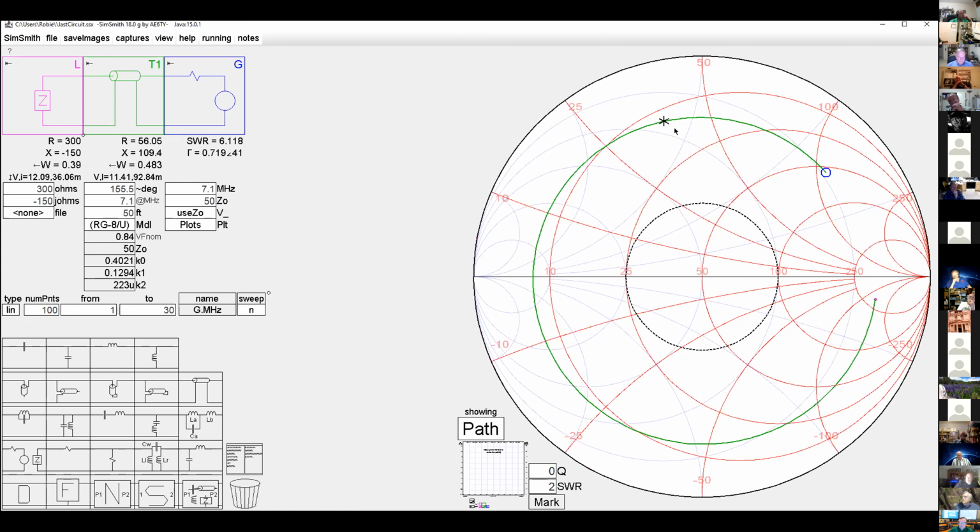And it was totally experimental. I would find a value that worked for the troublesome band, and then I would go back and recheck my other bands. On several occasions, I found that just adding that small length of line did not substantially upset my other bands, but allowed me to match on the troublesome one. In almost all cases, I was raising that low resistance value to a higher value that my transmatch, or my matching box, or tuner, whatever you want to call it, could handle.